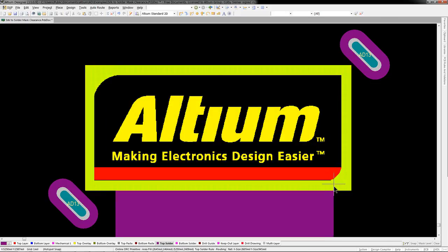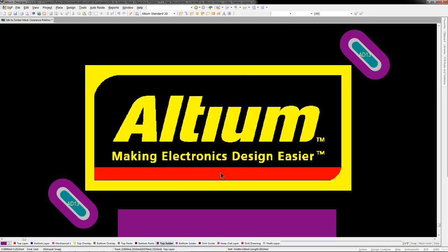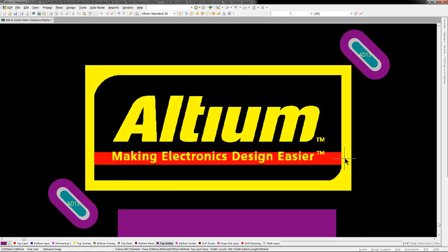As boards go to manufacture, areas like this may have the silkscreen trimmed, which can sometimes lead to illegible silkscreen text in trimmed areas. With this new expanded design rule check, you can detect and adjust your silkscreen locations for these occurrences prior to sending the board to manufacture, confident that your silkscreen will come back as you designed it.